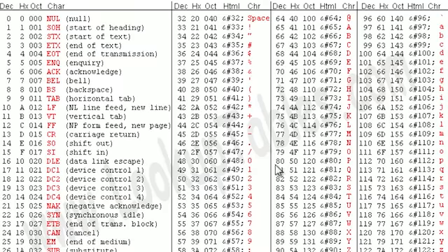Okay, so here's what our problem is. We're clearly sending this, but telling it it's an integer, when really it's not an integer that we're sending it, it's a char, which is really a byte of data. It's different. So we need to handle the conversion on the Arduino end so that we print back out the right stuff. Let's go do that.